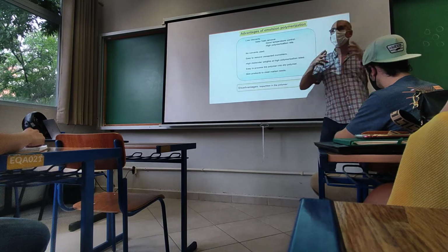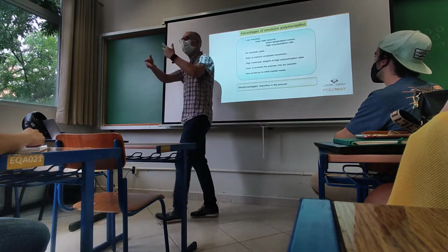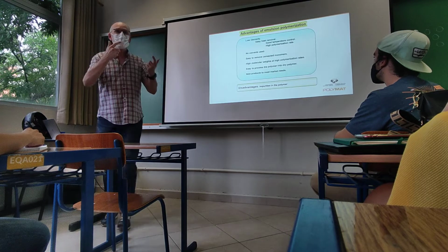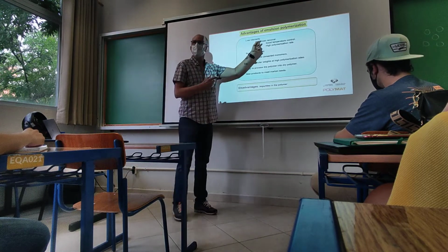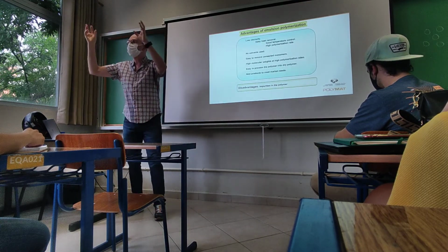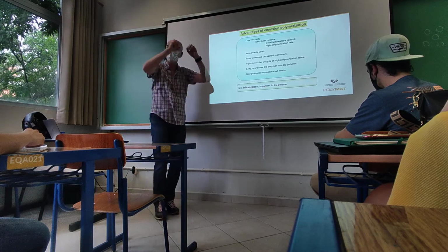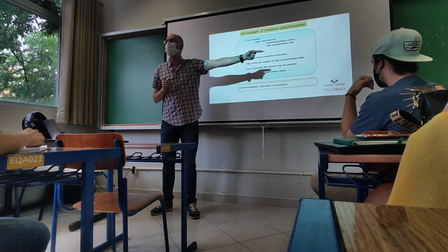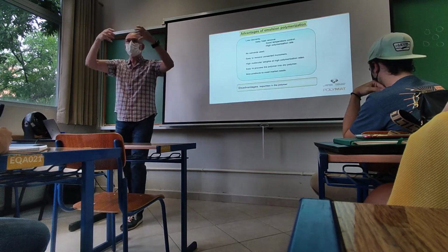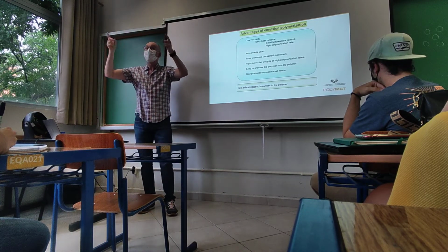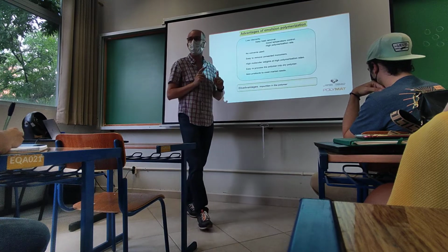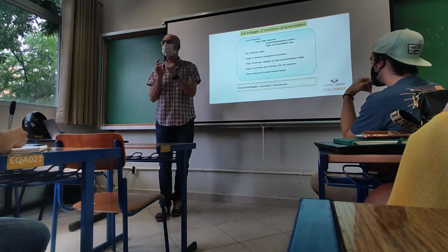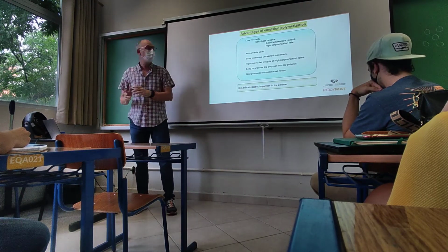As compared with homogeneous systems, where the polymer is dissolved in a solvent, the advantage is low viscosity, because the viscosity of a dispersion is not given by the concentration of polymer, but by the size of the polymer particles and the concentration of the polymer particles, but not by the molar mass of the polymer. Okay, this is an important difference with respect to homogeneous systems.